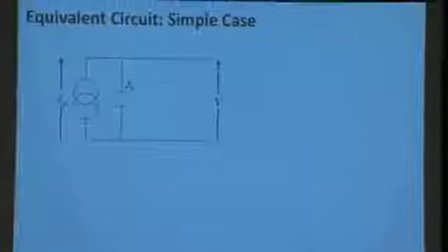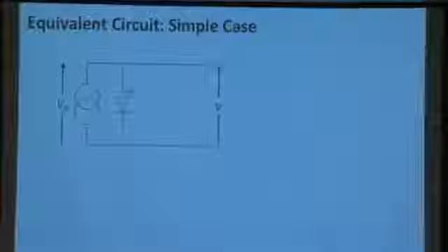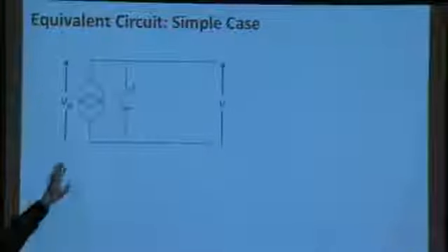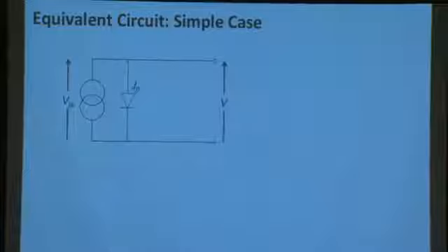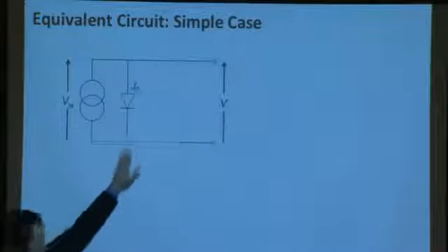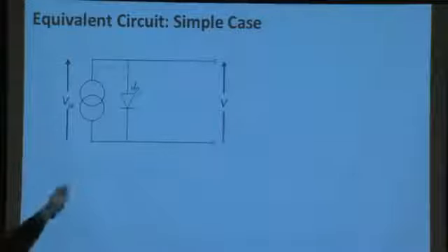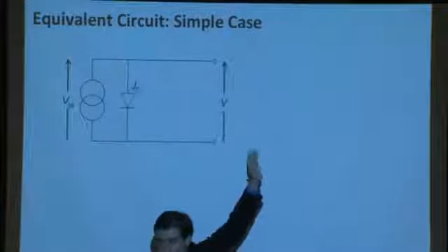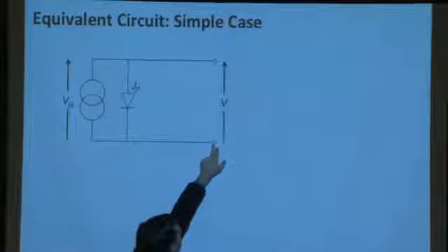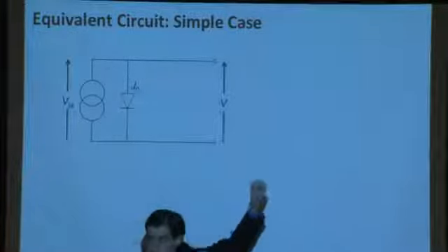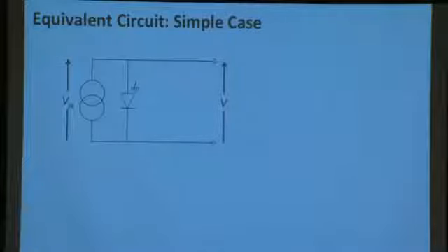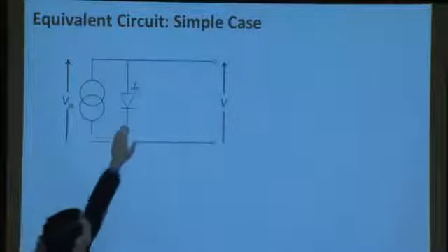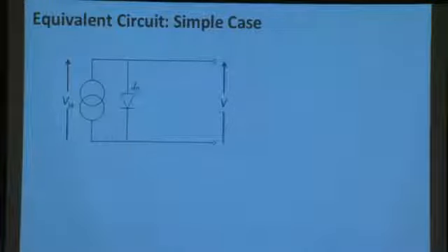So we'll start out with an equivalent circuit diagram of a solar cell device. And this might be new to some folks, but it's all stuff you've seen so far. What we have over here is the current generation source: the solar cell operating under forward bias conditions, under illumination, generating a voltage and a current. We have a diode here that prevents the backflow of current and forces the current to go out through the external circuit loop, right? And it forces it to drive the external load, which would be attached to that little circle over there and that other little circle over there. So you can imagine an external circuit attaching itself right there. So if the diode quality is high, if it's good, it will prevent the backflow of current.